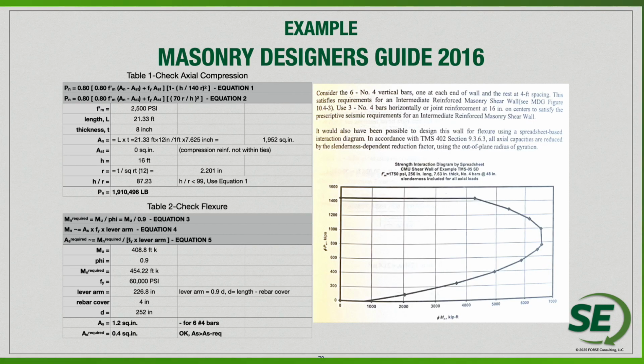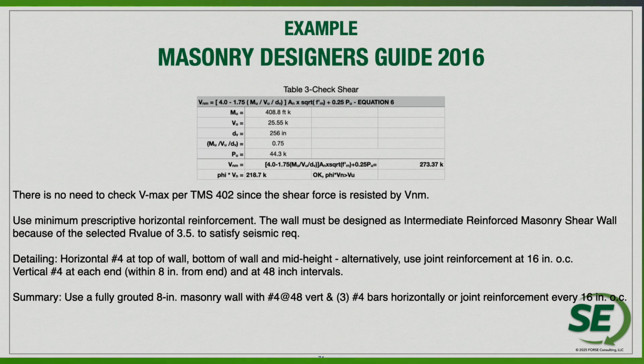You're going to see for this shear wall, we're going to develop that axial to moment curve to see what the pure bending and the pure compression forces would be, and where the actual balance point is going to be for the design, so we can see what the overall capacities would be for shear, moment, and axial forces. So here you can see shear capacity is going to be determined from the moment and shears and the overall length of the shear wall that we have considered.